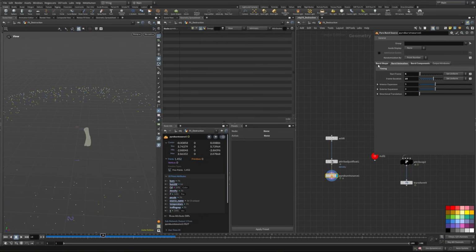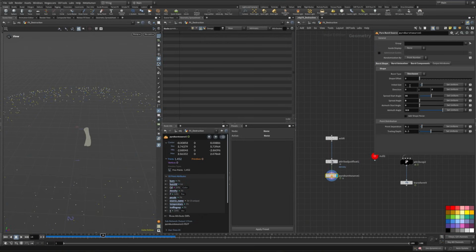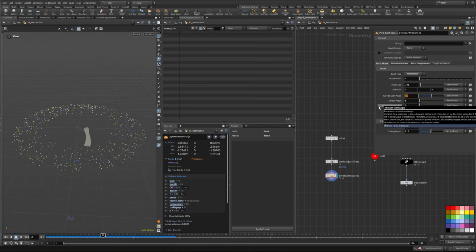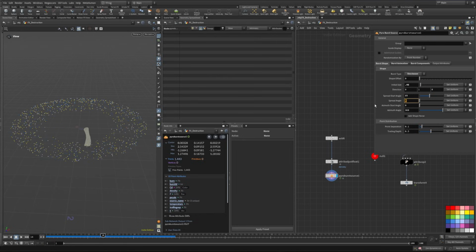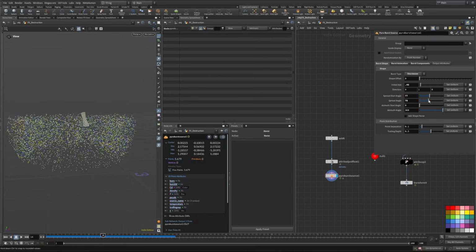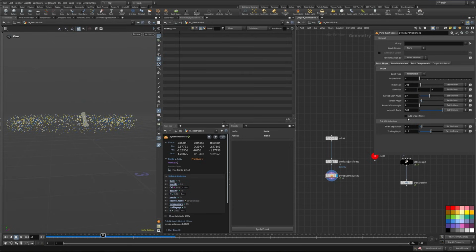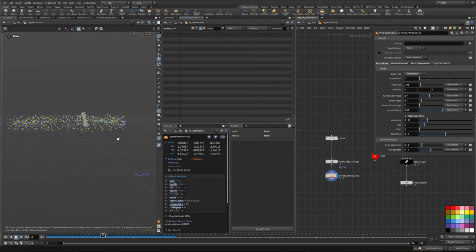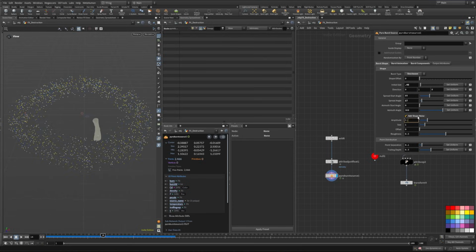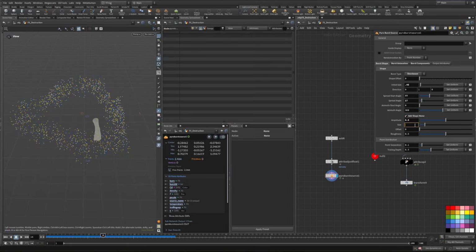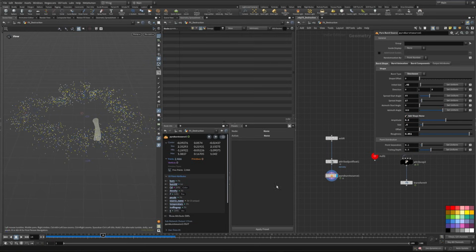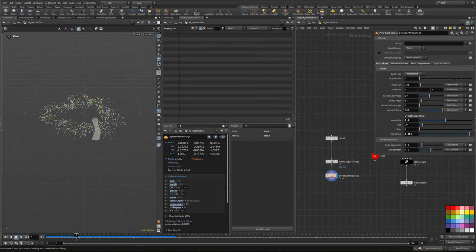And now let's get back to the burst shape. And I will lower the initial size to around 0.45. A start spread angle of around 77 maybe. And let's also give it a little spread of around 17. So it's getting a little bit bigger here. And we also want to add a noise here. So it's a little bit more random. Now let's use an amplitude of 5. Size of 0.6 maybe. And a really high roughness here. And it is looking pretty cool.